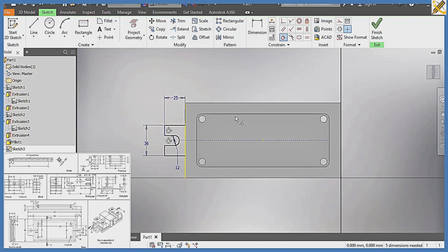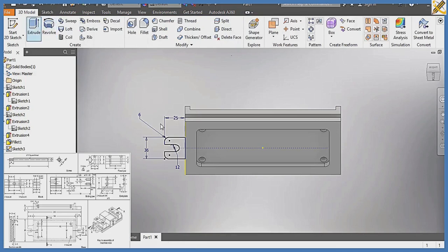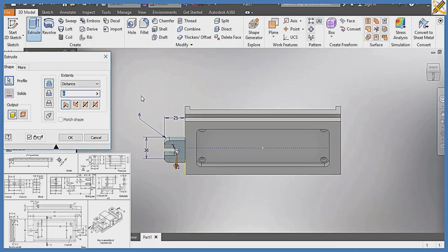All right, so that area settled, then pick my line also, join this down here. All right, so that is that. I'm going to actually use the mirror constraint here. Okay, so I'm going to pick my fillet of radius 6, in that order. I'm going to stand right here to here. Okay, then I'm going to click this, then finish sketch. So finishing my sketch, I'm going to click on extrude. I'm going to extrude that particular area as 12.